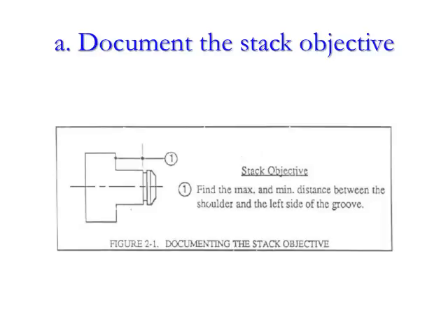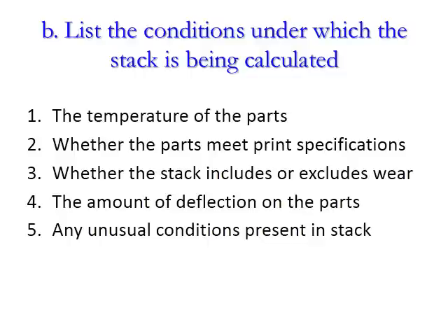Document the stack objective. The stack objective here, from the drawing shown, is to find the maximum and minimum distance between the shoulder and the left side of the groove. List the conditions under which the stack is being calculated: the temperature of the parts, whether the parts meet print specifications, whether the stack includes or excludes wear, the amount of deflection on the parts, and any unusual conditions present in the stack.